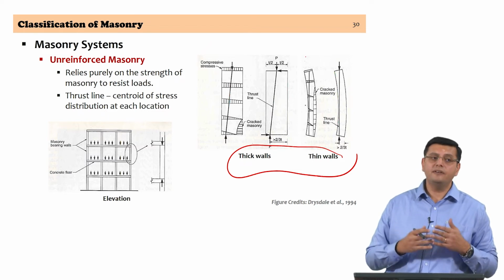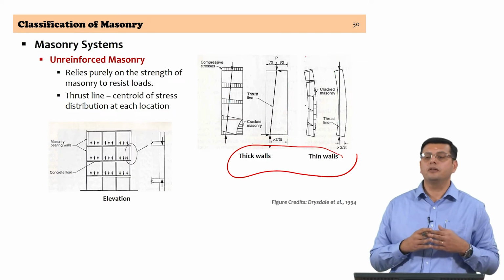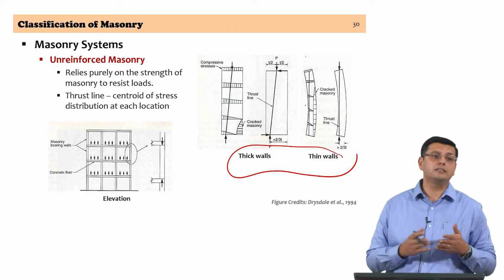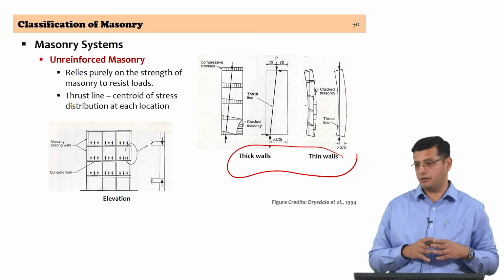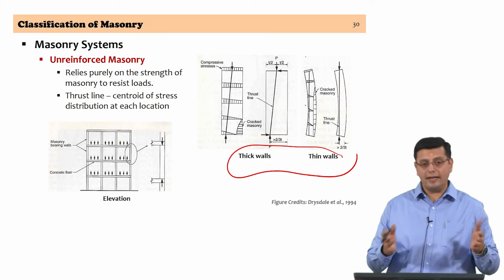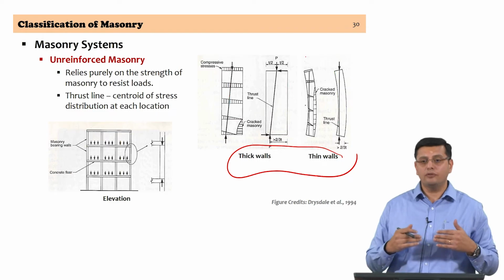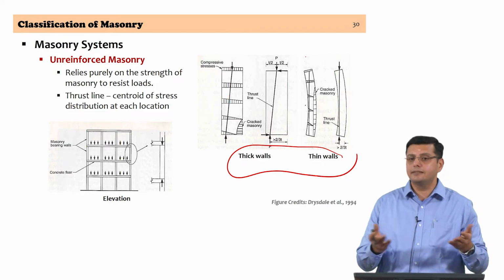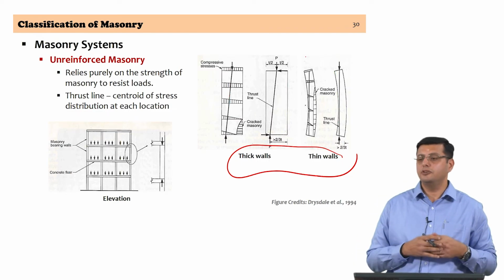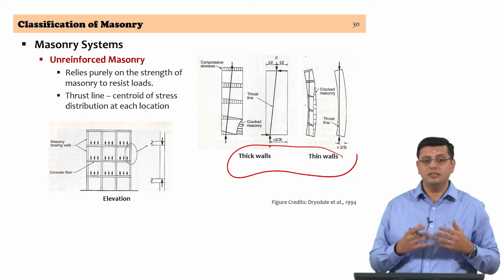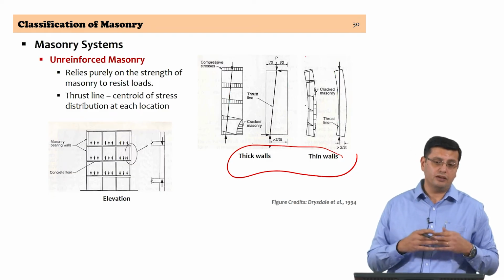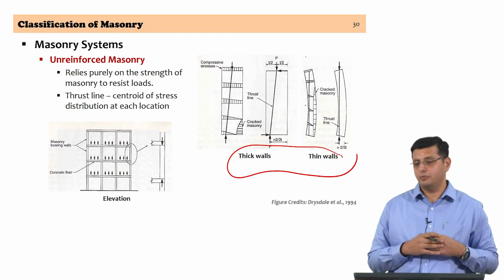However, even if seismicity is low, we can't classify any zone as being completely aseismic. In case of an accidental loading, even due to a low magnitude earthquake or low level of ground shaking, these structures can get into the inelastic range, which is not desirable.